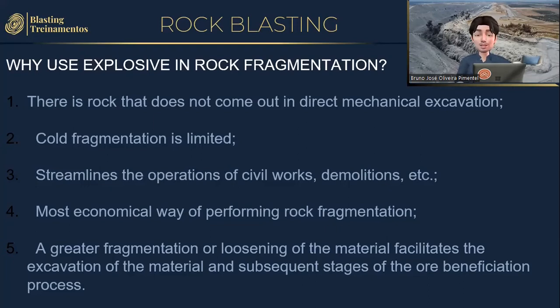We still have the fourth point, because the use of explosives is the most economical way for us to fragment the rock. There is no other energy or method as cheap as the use of explosives in rock fragmentation. When there is any need for further fragmentation, for loosening the material, or for a larger release to facilitate excavation, and also to facilitate the following steps in processing that material, the energy of the explosive is the cheapest energy one has to carry out this work, giving a high productivity, in a more economical way and to meet any scenario.